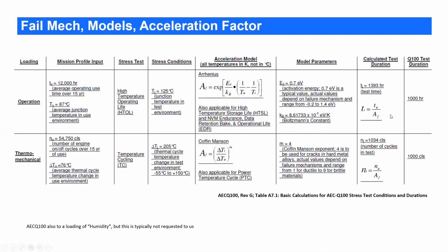Okay. In the AEC Q100, the qualifications shall be run only at 1,000 hours. This is just more or less an arbitrary set point, where at this point in time, the AEC committee said this is fair enough to estimate the reliability of an IC.